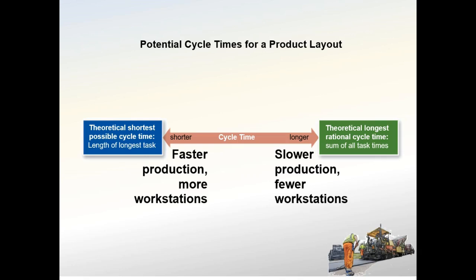First, to determine the cycle time for the layout. Next, to draw a precedence diagram illustrating the tasks requiring assignment along the path of the layout. Next, to assign those tasks to workstations along a predetermined decision rule. And finally, to evaluate the efficiency of the resulting layout. The design of a product layout is essentially complete at the end of step 3, but since the procedure cannot guarantee this design is best, it is wise to evaluate it for comparison with other designs.